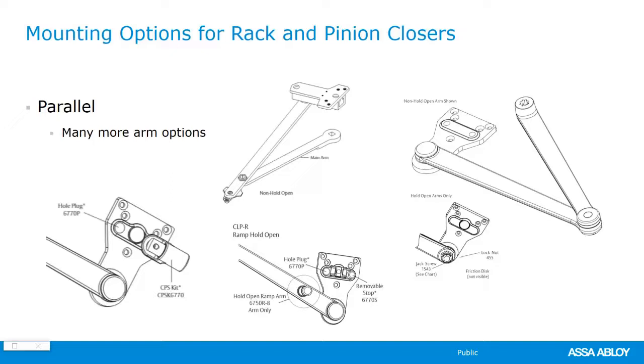Perhaps you have a full glass frame outside wall that's just all glass, aluminum frame, something like that, and just not really a good way to put a wall stop on that. Floor stops collect dirt and dust and are tripping hazards and all kinds of issues, so floor stops are not a good option. So you can add a positive stop or a compression stop, a spring stop, all kinds of different options with the parallel arms.